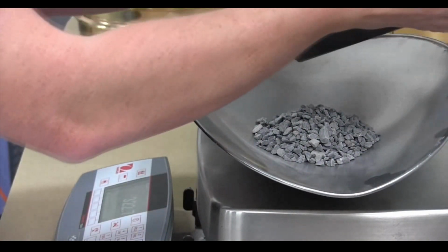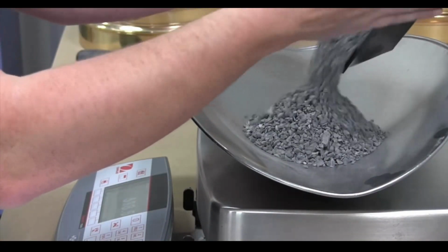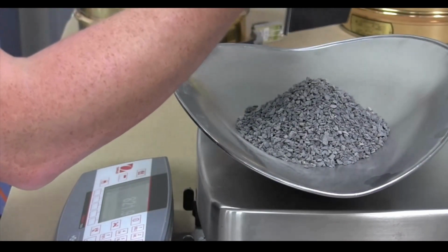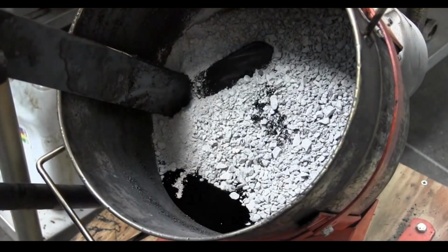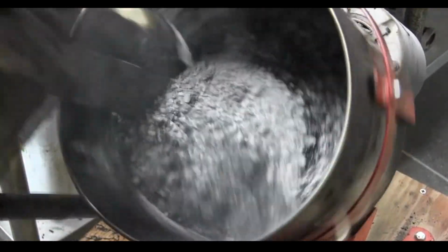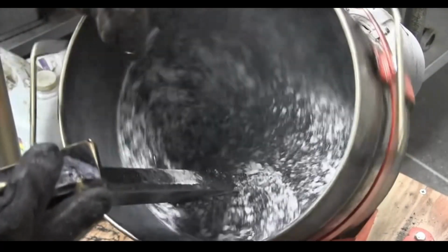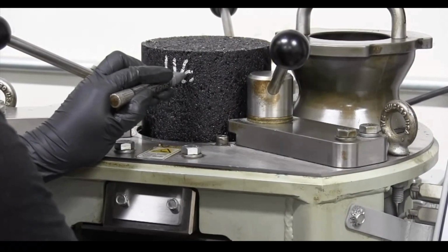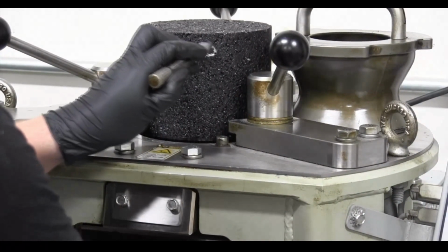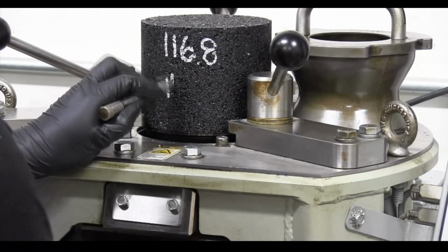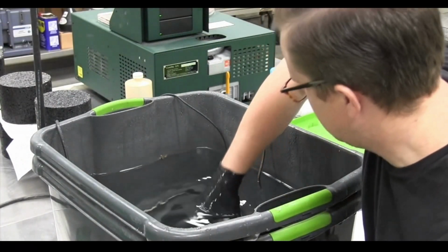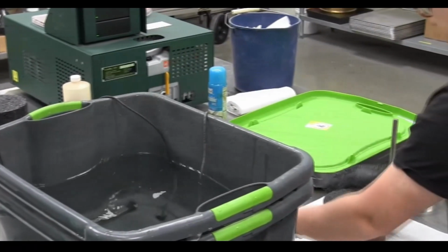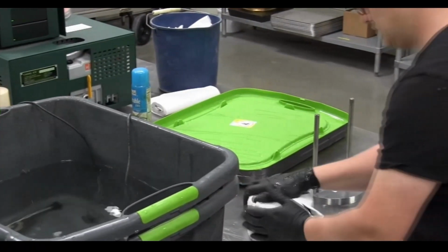Like a recipe in baking, the mix design determines the proper blend of materials needed to produce the desired asphalt mixture during full-scale production. Technicians will first produce small batches of the mixture in the laboratory and perform a battery of tests. The asphalt material is compacted in a lab machine, producing what is commonly called a pill. The technician will test pills for several engineering properties, including susceptibility to water damage, the amount of liquid asphalt, specific gravity, and the amount of air voids, or space between the rocks, present.